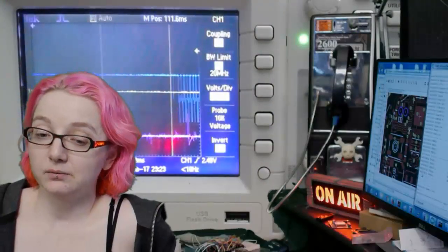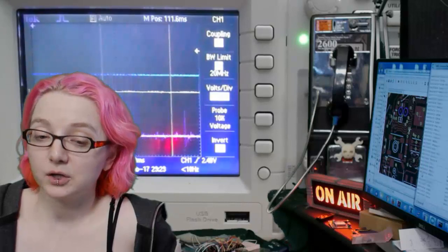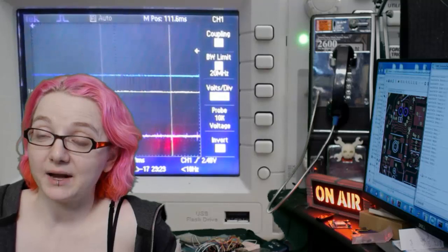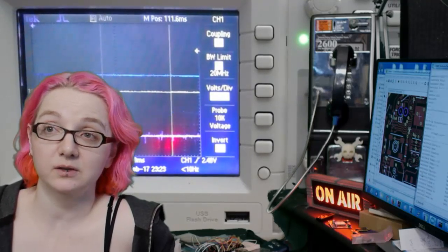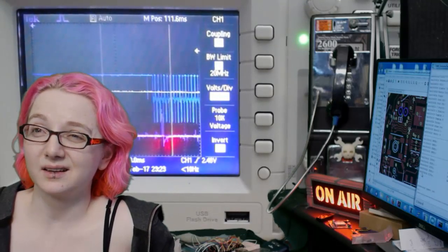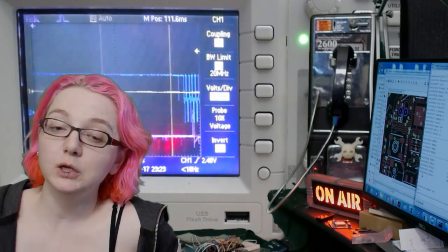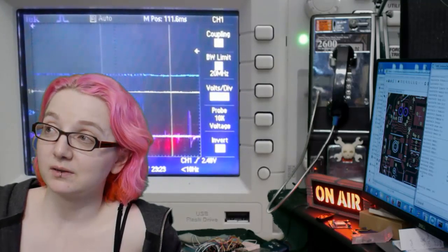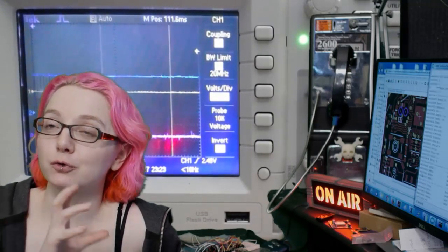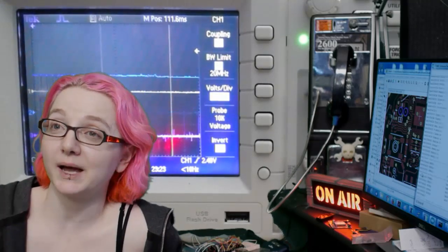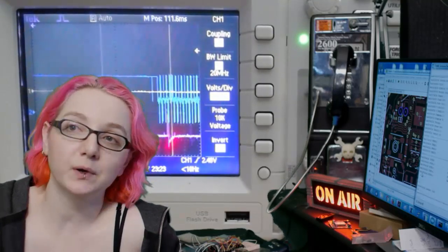Well, you'll want to get whatever charge controller is for that panel. That panel probably has a recommended lead acid charge controller or something, and then you can connect a battery to it, and then you would use a buck converter from that battery. So you need to have a battery. You can't connect it directly to your phone. It's just not a good idea. It's better to charge a battery, and then use whatever battery it's charging to charge your device. But you need the charge controller for the battery. There's something that takes a solar panel and charges the battery. Wherever you got that solar panel from, they probably also sell the charger.